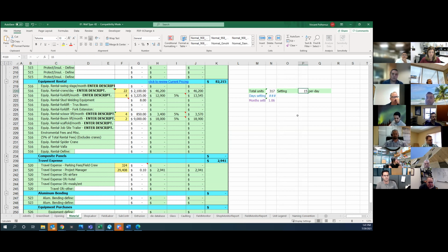If TJ plans that we're going to have a forklift for 4 months, we have it for 5. We take whatever the durations are supposed to be in the field, and we round them up. We take all the hours that we're supposed to have in the field to do a job, calculate the equipment, and round it up, and then beyond rounding it, add 1. So if you did the calculations and you needed a boom lift for 4.5 months, we'd round it to 5, and then we'd add another 1. We'd get to 6. You adjust that depending on what GC you're working with, but today this is a standard that we do across the board with everyone.